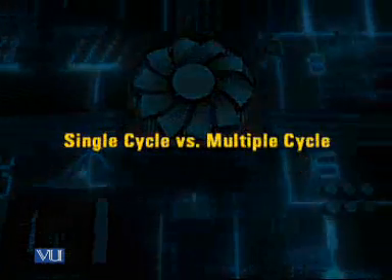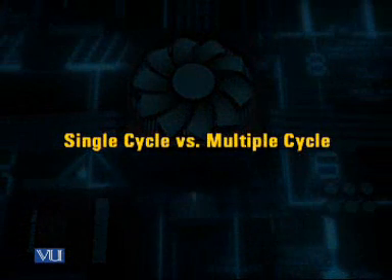For example, if the single cycle design requires a cycle length of 5 microseconds, determined by the total time required to fetch, decode, execute, perform the memory operation, and the write back operation, this total time can be divided into smaller steps, and each sub operation can be completed in one small step.